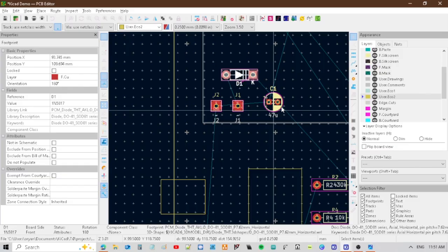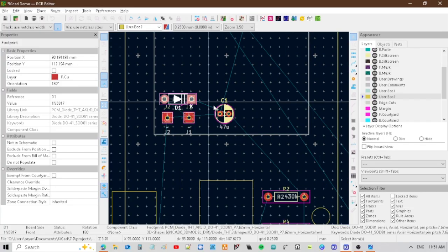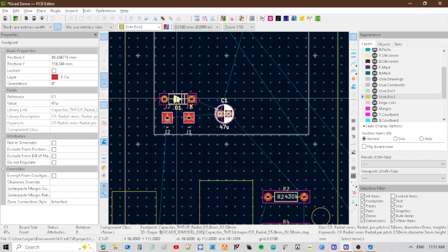And now I'm going to have this rat's nest coming back this way so that I can work the trace like this and then into the board. I'm going to take my filter cap. Actually, you know what? I'm going to leave a little space because I'm going to use a ground pour. It's the best way to do this.